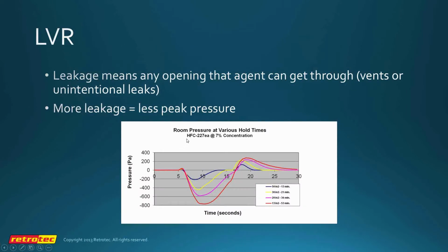So here we have FM200 essentially going negative and then going positive. The different curves here show the different enclosure leakages, and as the enclosure gets tighter, the negative peak pressure and the positive peak pressure, it's not quite linear with enclosure leakage, but it's reasonably close. So we can see here with the most leakage we have the smallest pressure spike.